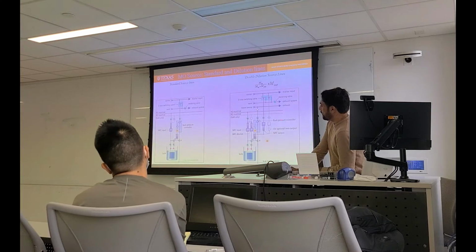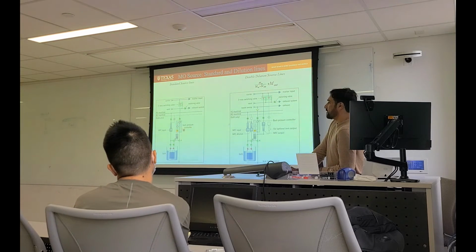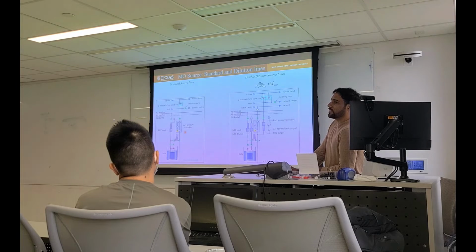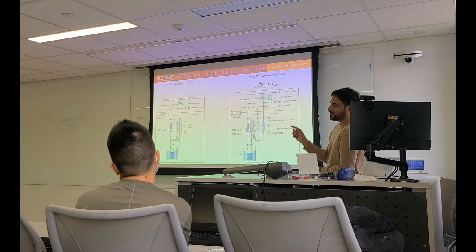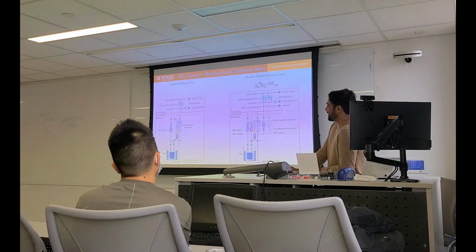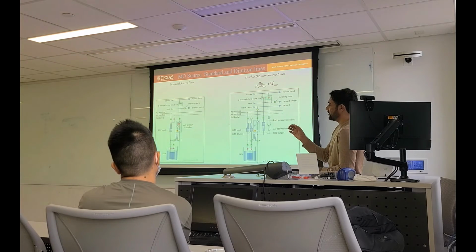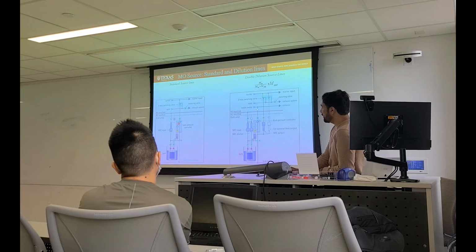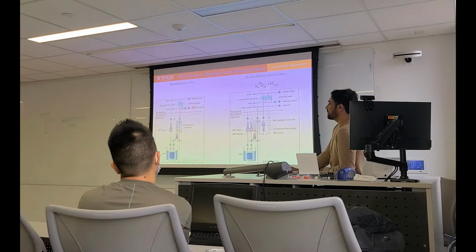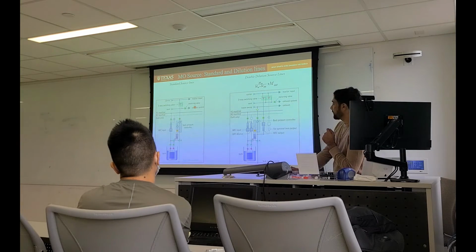This pressure controller is actually the EPC, electronic pressure controller. If I did not answer your question, you can ask me again here. You flow your carrier gas inside the bubbler. It carries the source and passes directly through the EPC, and moves directly to the reactor or to the exhaust if you want. You can control it.